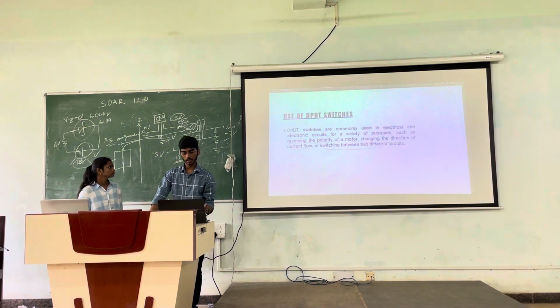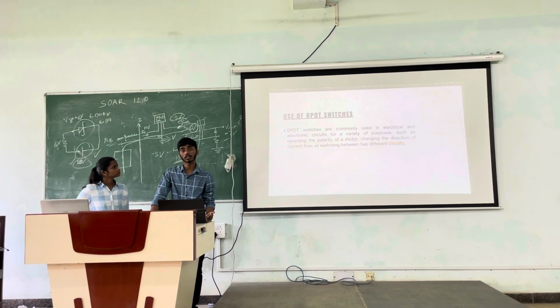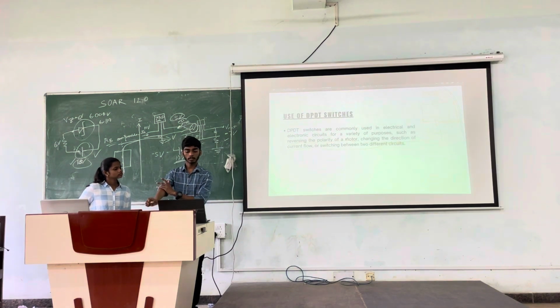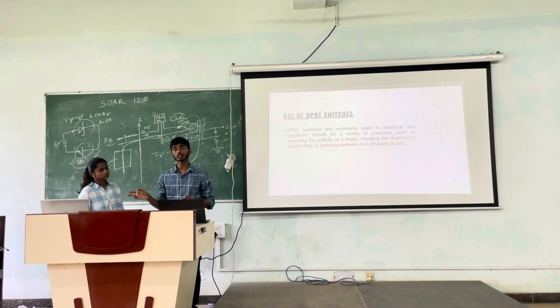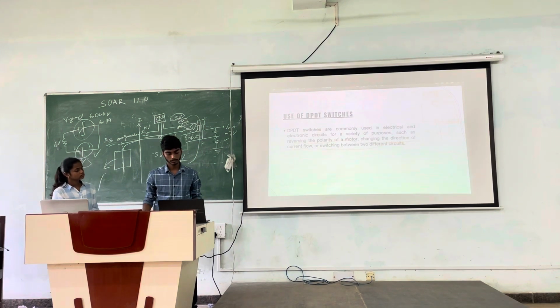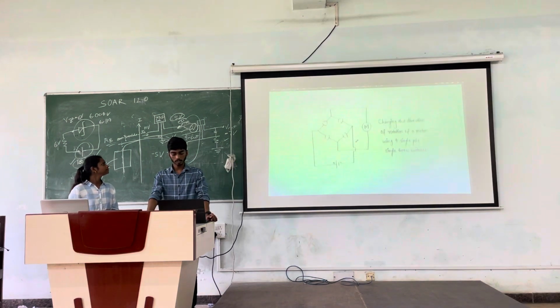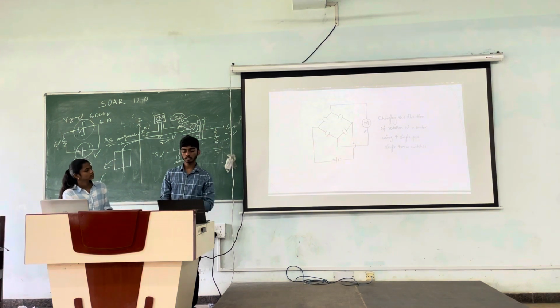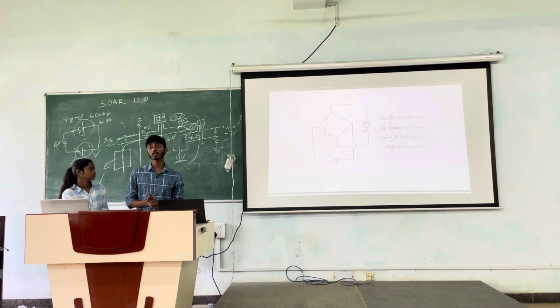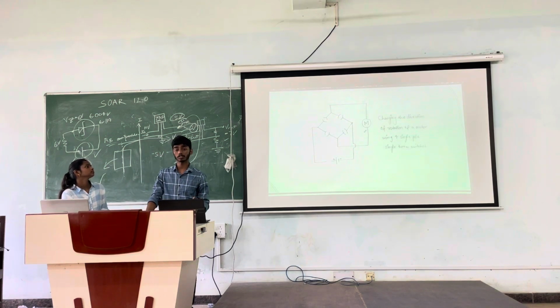Coming back to this part, we have seen the application of DPDT switches in reversing the polarity of a motor. Let's say our aim is to reverse the motor polarity, like reversing the direction of rotation of a motor. We need to change the polarity across its terminals to reverse its direction. Let us try to achieve this using single pole, single throw switches. We will require 4 SPST switches for this configuration first. We'll move to DPDT switches later on, but let's understand using single pole, single throw switches first.